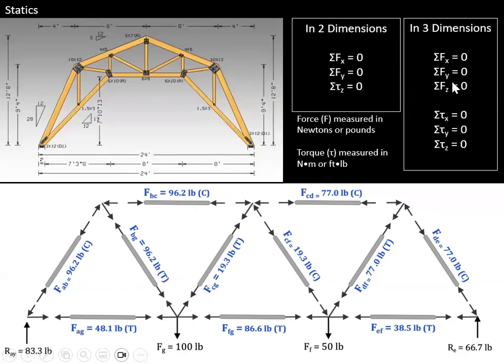Now, you guys know the foundational knowledge for statics is these boxes right here. I made a poster just for this. So, equilibrium: sum of forces goes to zero, sum of torque goes to zero. That's it. There's your starting point. Here I have a 2D version, and here's a 3D version of that. But force and torque go to zero.